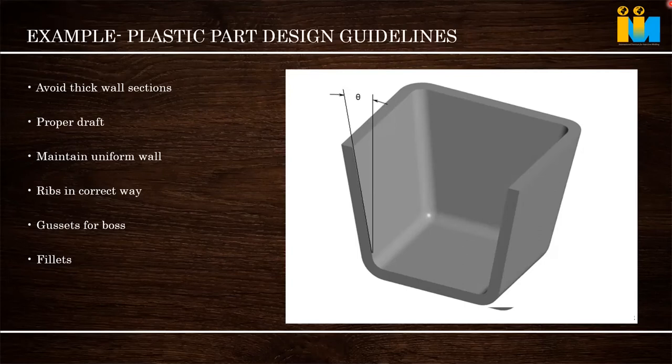and the ejection pressure is also more. More ejection pressure means more electricity is consumed by the molding machine. So a generous draft is always advisable. There is no limit to the draft you give. Give whatever is possible. Give 2 degrees, 3 degrees if possible. Don't restrict to quarter degree, half degree and so on wherever it is possible. In some areas, if the function calls for it, okay, leave it with a lesser draft. But don't leave any part without draft.